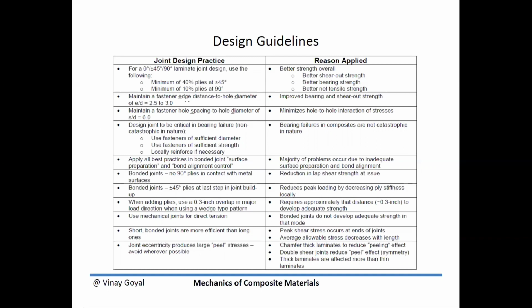effects between holes. Recall that each hole can cause a stress concentration. If it's too close to another hole, then these two holes will have a stress concentration of their own. And their respective stress concentrations will then potentially overlap and cause a serious issue.